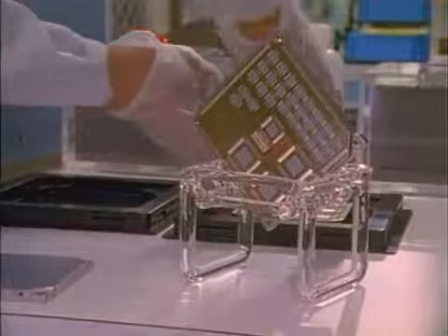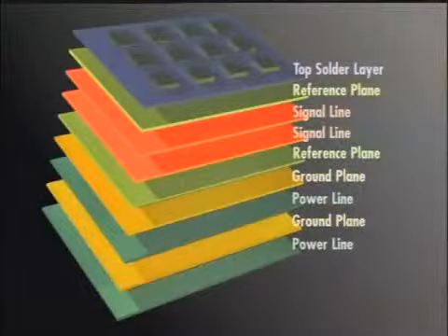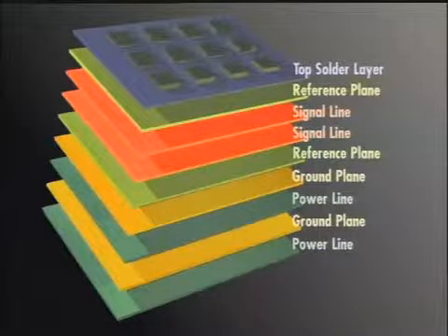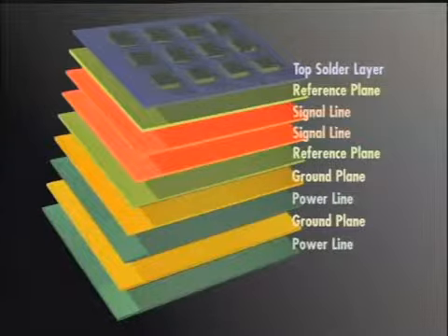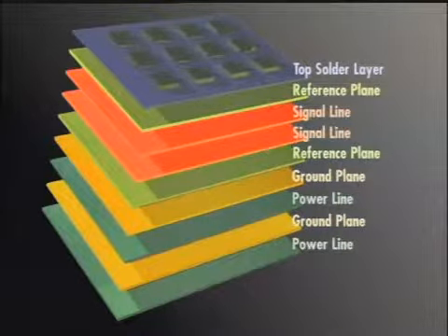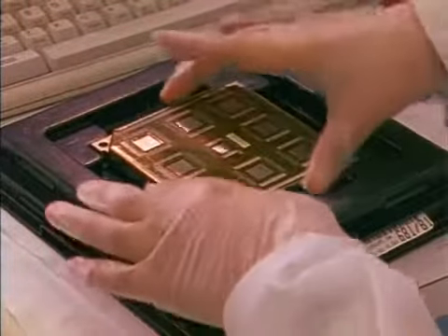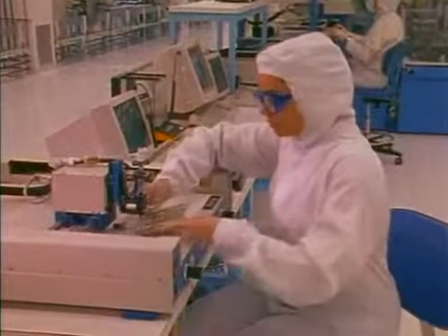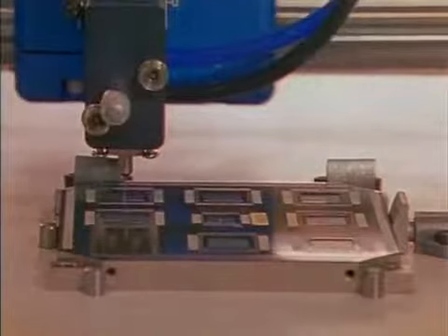The board of the MCU is a high-density signal carrier substrate. It consists of 9 interconnected metal layers, insulated with polyimide coating, and fabricated using semiconductor technology. The top layer is used to solder attach all the integrated circuits and connectors. This signal carrier, with its 3,000 to 4,000 solder bonding pads, has been cleaned and prepared for the attachment of high-powered chips.